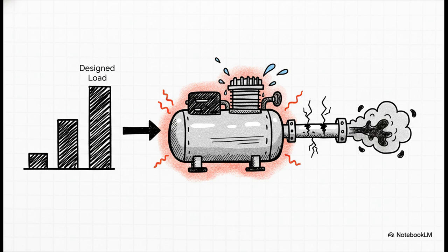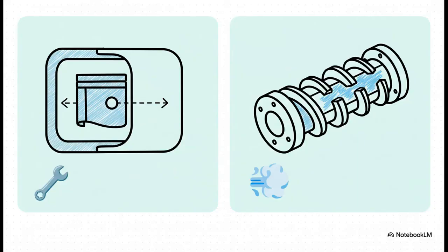And here is the culprit. See, the compressor was sized for the original designed load of the factory, but after years of these tiny leaks adding up, the actual load is way, way higher. The machine is running constantly, 24/7, just to keep up, and it's overheating. And as it overheats, its oil-based lubrication starts to break down and get carried over into the airstream. That's our contamination. So a replacement is definitely needed.